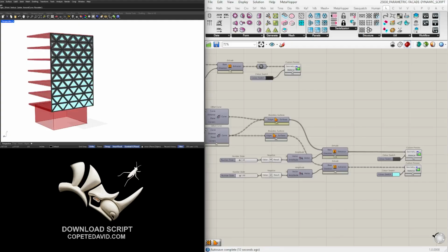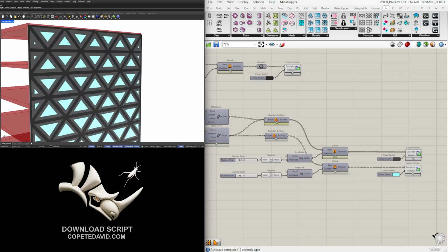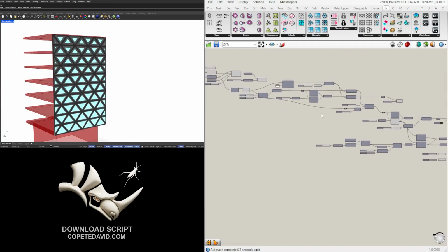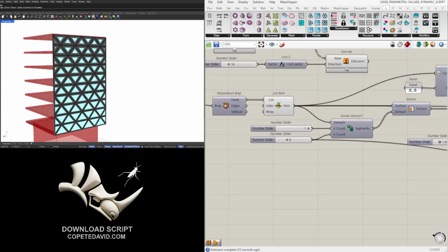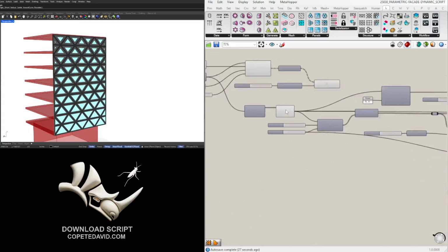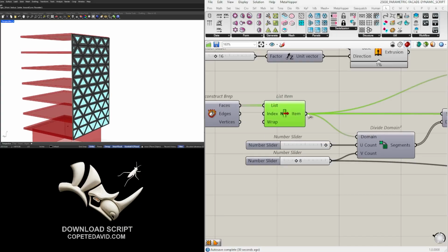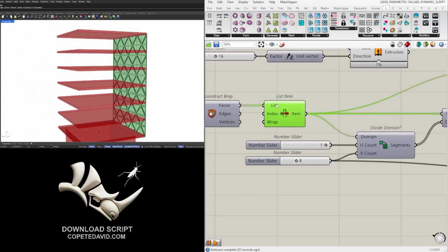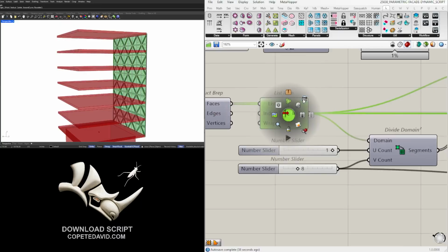So now here towards the end, if you've been wondering, well, all we've done is one side. Can't we do the other sides? Well, that is one of the great things about when you do the script for one, and if you've done things correctly, you can do it to all of the other sides. So we picked only one surface here, but if we go to this list input, now keep in mind, the larger the subdivisions you have, the harder it is to compute this, and it could even crash your computer.